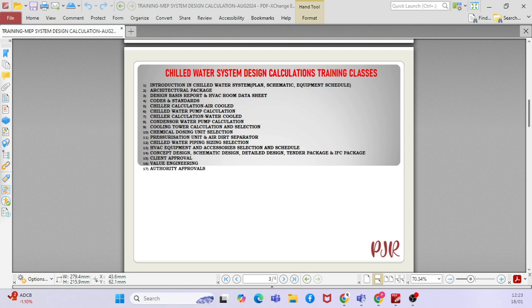So why is the chiller required? It is required to absorb the heat from the indoor unit. For example, you have a chilled water system. There is chilled water piping between the indoor unit, which is called the fan coil unit or AHU, and the chiller. What the FCU or AHU is doing is absorbing the heat from the space, and that heat will be rejected in the chiller. The chiller has an evaporator and a condenser. The evaporator will absorb all the heat from the chilled water, then it will be discharged to the condenser by means of the refrigerant pipeline.